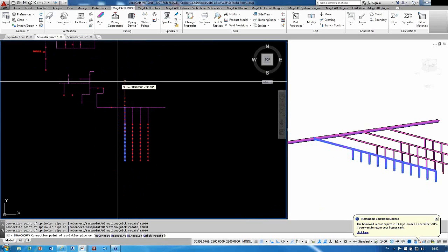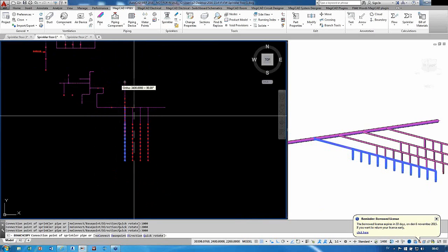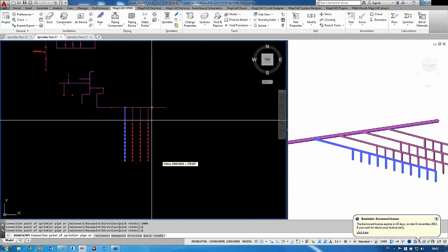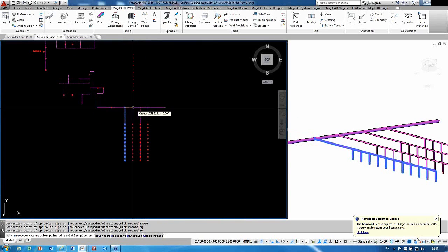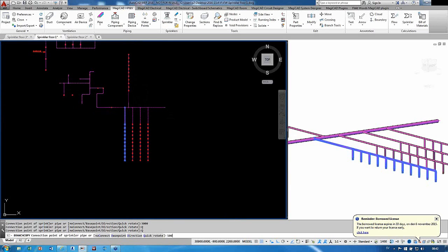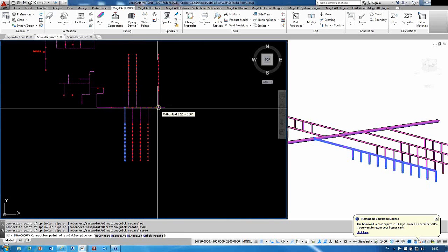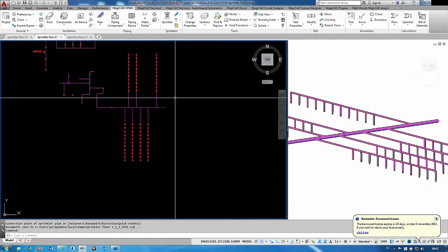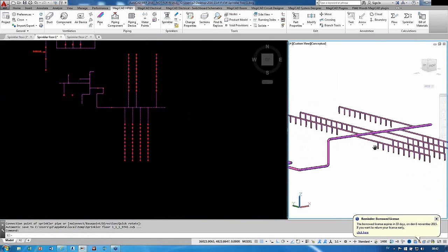And if I want to have them in the other direction, I can also take a Q for quick rotate, and then I do the same, but now I say 500, I say 1.5 meter, or of course I can just point here, so then we have made, first I draw one branch and then I copy it, and I also copy and rotate.